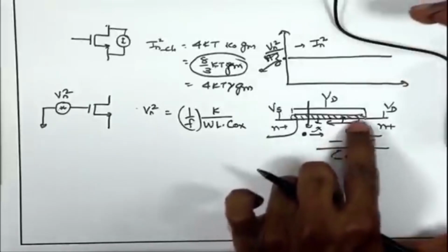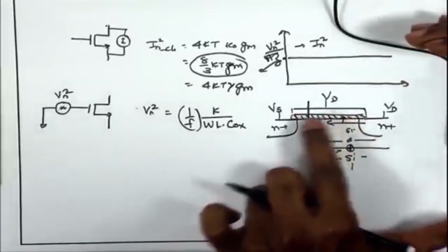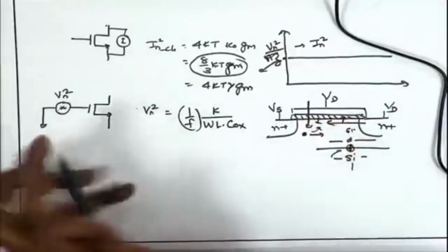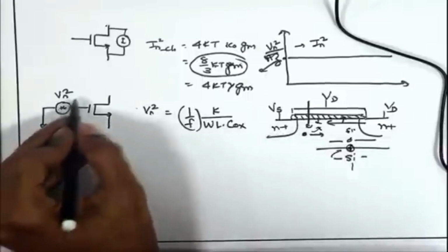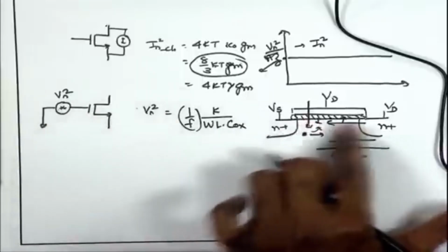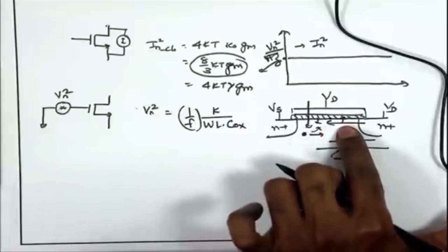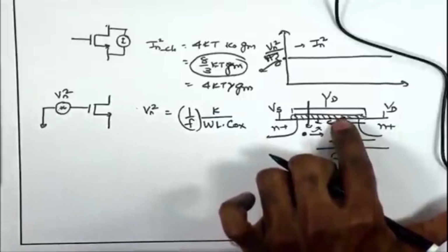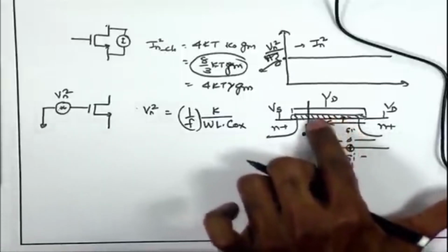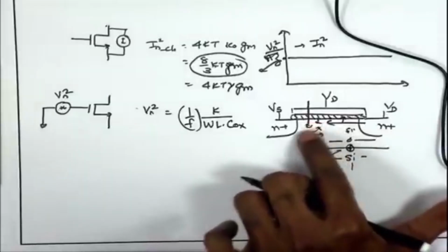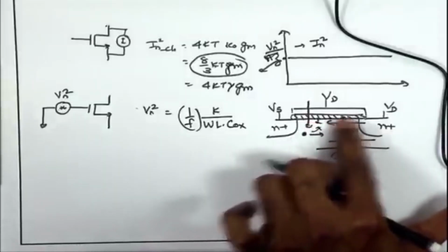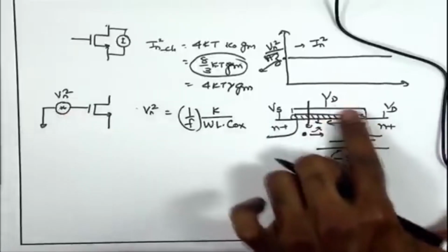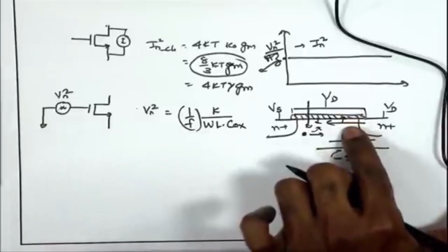So, threshold voltage can fluctuate whenever you are having these negative charges getting trapped and detrapped from this oxide surface. So, for example, whenever you are trying to increase the gate voltage a little bit, you expect that the channel charge will go up by a proportional amount corresponding to Gm, but if you are ending up increasing the trapped electron charges over here, the increase in channel charge will not be so much, because some of the trapped negative charges are compensating for the additional positive charge that you have put on the gate. Therefore, it will fluctuate from the desired value.